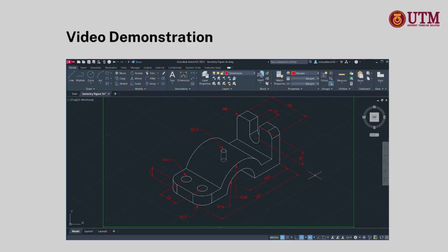So using this as an example, for mechanical equipment drawing requirements like pressure vessels, tanks, and piping, the drawing must include more than just the object shape. In this case, you can see that the drawing has not just the white object, but the red dimensioning as well. So it must include the overall dimension, which shows the total size of the equipment, such as the full height, full length, or outer diameter, and the wall thickness, if applicable. In this case, you will have wall thickness represented by these 11 units.